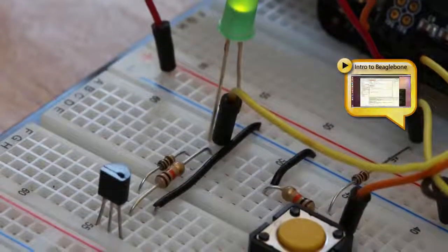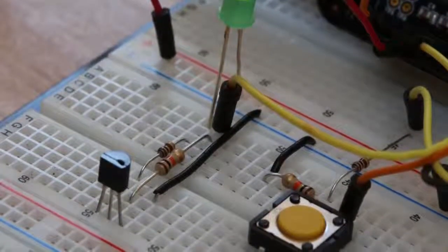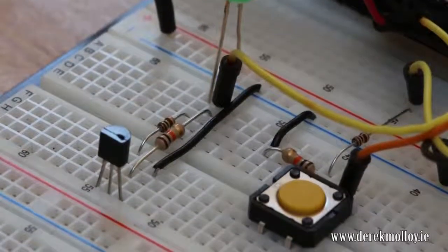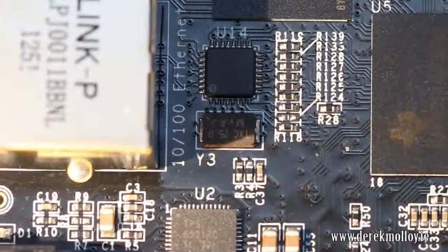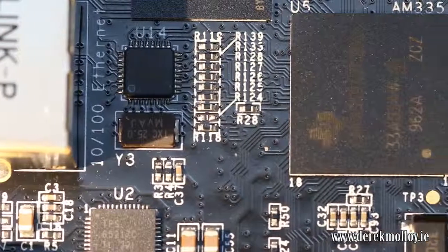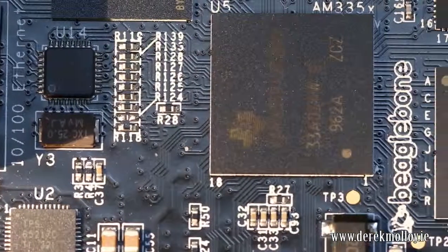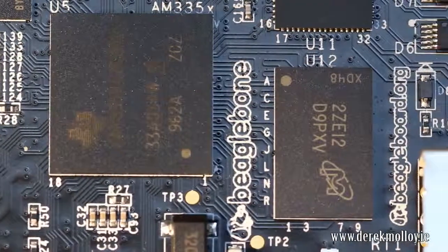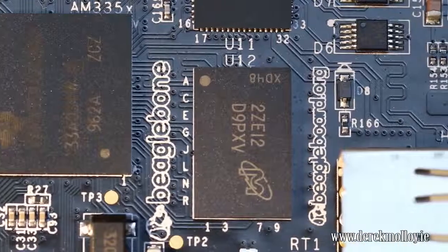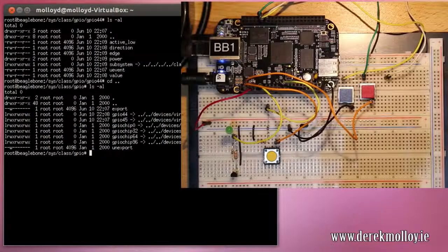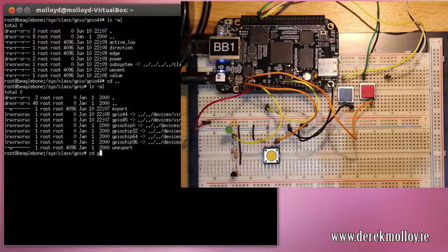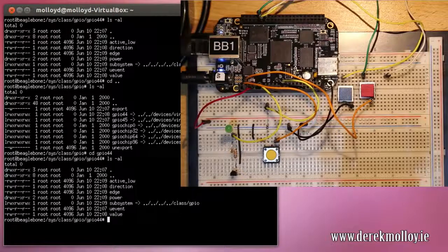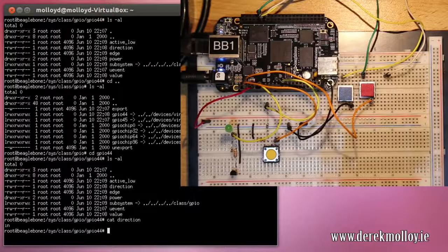I covered this topic before in a previous video about a year ago, but I am updating it because there have been significant changes to the Linux kernel that make my previous video dated. This video will cover the Linux device tree for ARM embedded systems and explain how you can create custom device tree overlays to configure the GPIOs for your application at runtime from within the Linux user space. I will explain the use of internal and external pull-up and pull-down resistors, and I will make available and describe a set of C++ code examples for reading and writing to the Beaglebone's GPIOs.